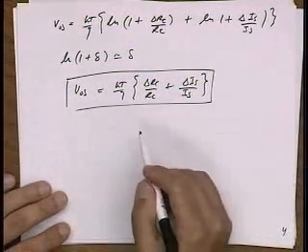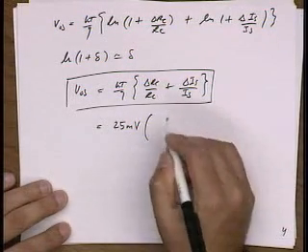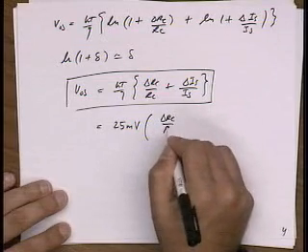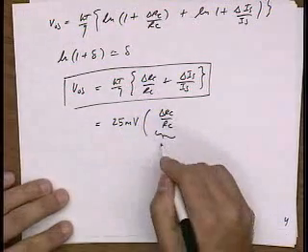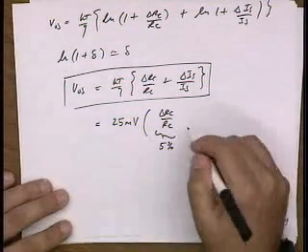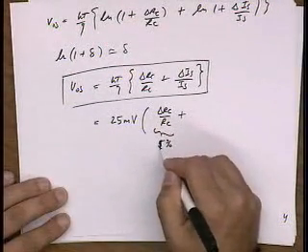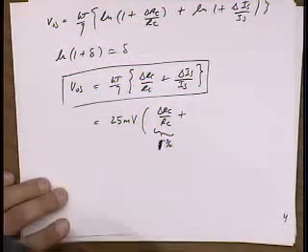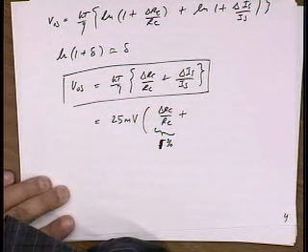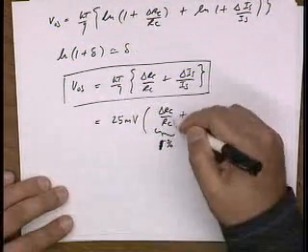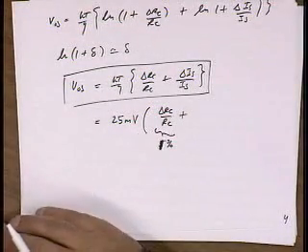All right, well, let's plug in some numbers. So KT over Q is 25 millivolts. And what's a typical matching I might get in resistors? I don't know. Let's say it's 5%. You probably can get better. Yeah, let's be fair. If this is a bipolar process, and you actually have, let's say, custom thin film resistors, remember, this is a matching between two resistors which are fabricated nearby. You can get very good precision. You can get 1%. Okay.